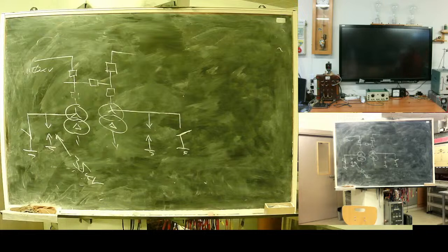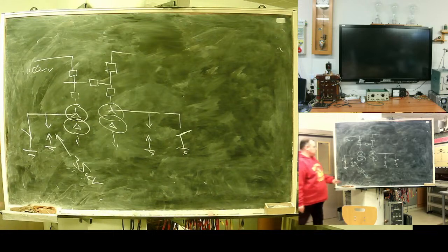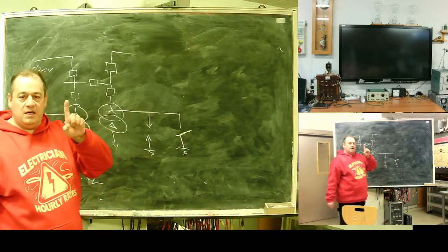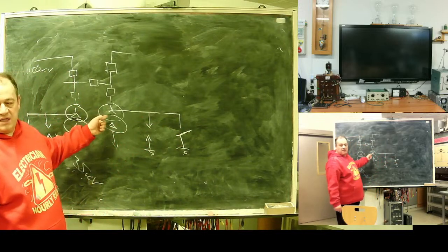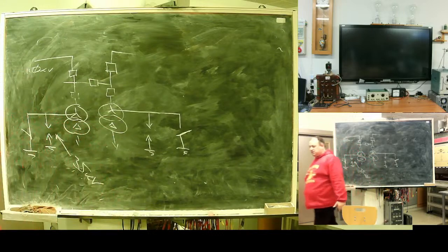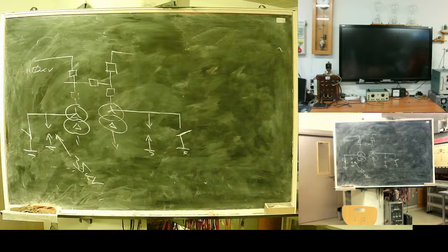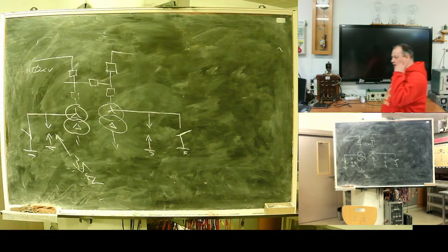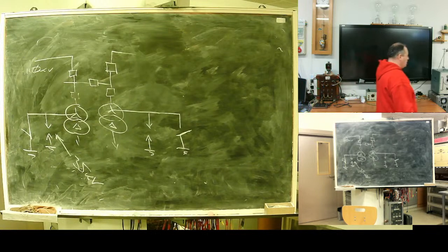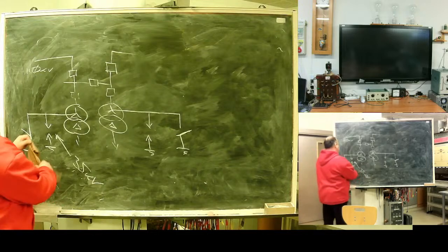One transformer operates or two, only one neutral is grounded. You switch the second one on only when connecting the transformer to the network or disconnecting from the network. Other time, only one neutral should be grounded. It's moment number one. Moment number two, important.